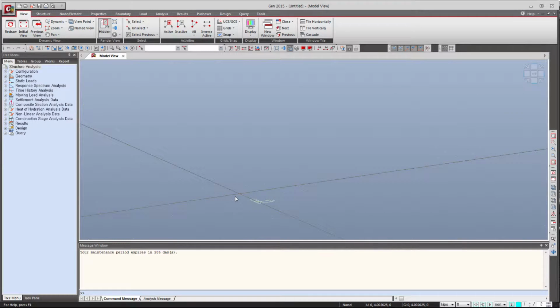The main one is called Global Coordinate System, or GCS, and the element coordinate system called the ECS. So the global is what is usually used, and then you have 2 specific coordinate systems, one for the node and one which is a user coordinate system, UCS, that you define by yourself. So here you see that you have UCS and you have GCS, so you can switch between the global or user coordinate system. So let's see how to do that.